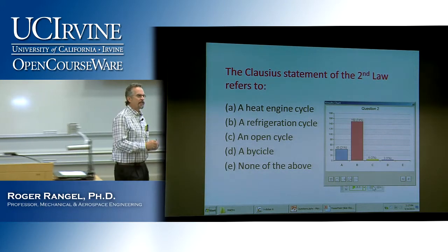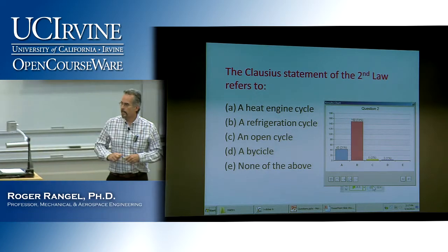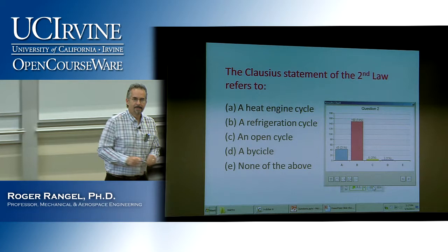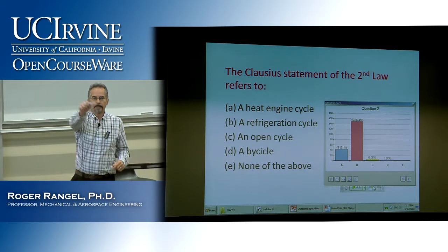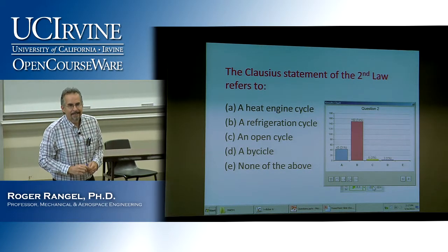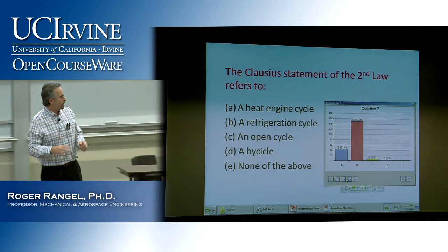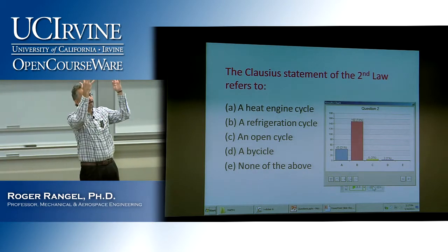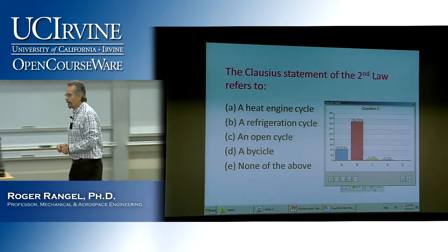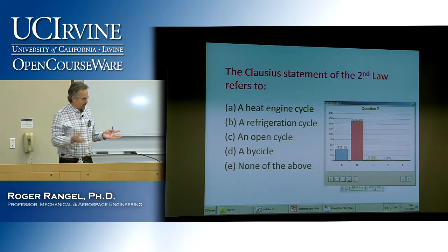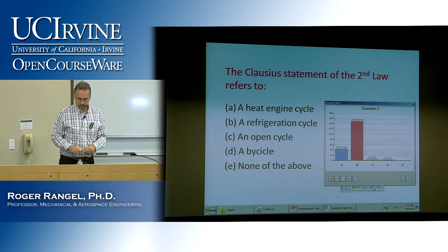In particular, what does it say? What does the Clausius statement say about this refrigeration cycle? Somebody over there or here. You can't take the energy from cold to a high reservoir without doing any work. Right. You cannot take the energy from the cold reservoir to the hot reservoir without putting any work in. I always say that, you cannot have a refrigerator that is not plugged in.